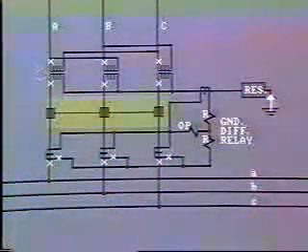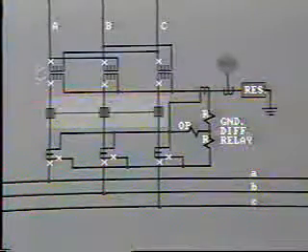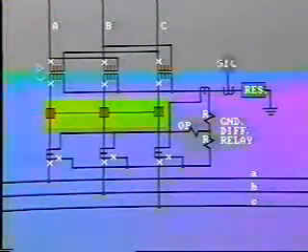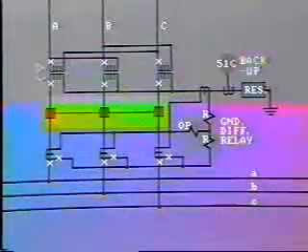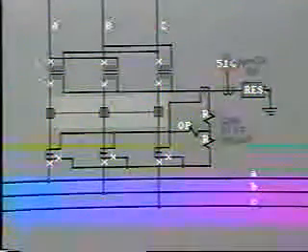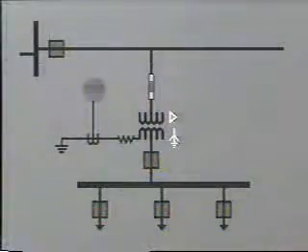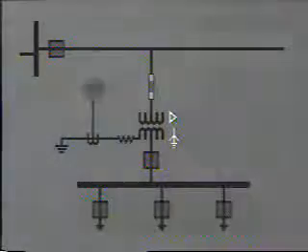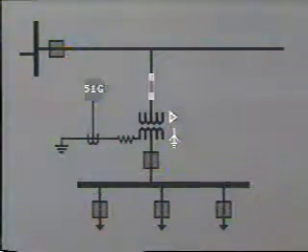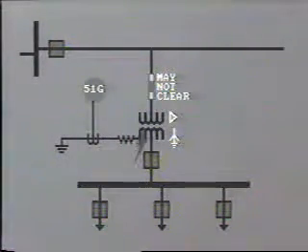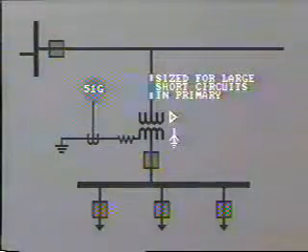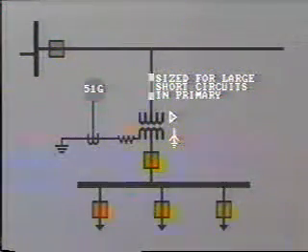Quite often with this arrangement, an additional time overcurrent ground relay, 51G, is installed in the neutral. This acts as backup for the transformer ground differential, and also as backup for ground faults out on the feeders. It must be correctly coordinated with protection on the feeders. The primary high-voltage fuses may not clear for a low-level fault on the secondary winding or the secondary system. They are usually sized to protect against heavy short circuits in the primary winding.